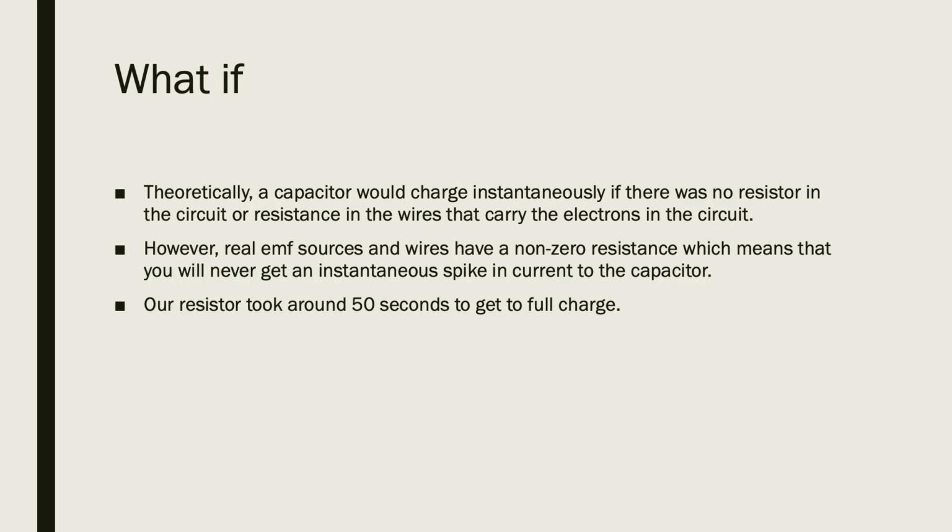What if we charge the capacitor without a resistor in the circuit? Theoretically, a capacitor would charge instantaneously if there was no resistor in the circuit or resistance in the wires that carry the electrons in the circuit. However, real EMF sources and wires have a non-zero resistance, which means that you will never get an instantaneous spike in current to the capacitor. Our resistor took around 50 seconds to get to full charge.